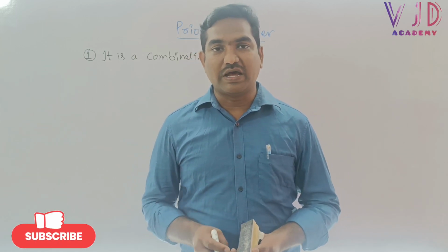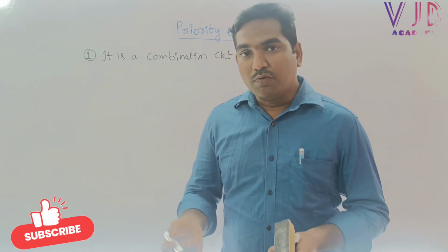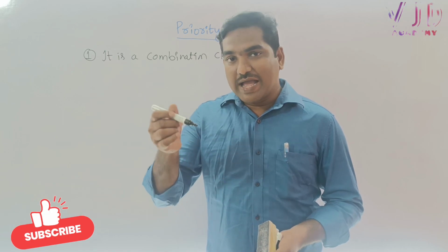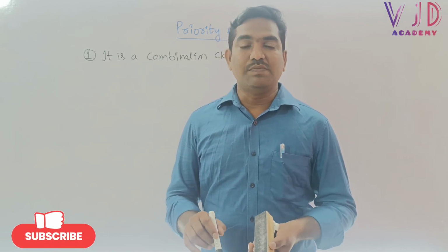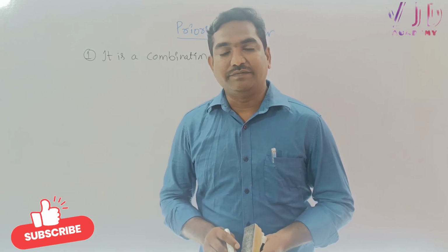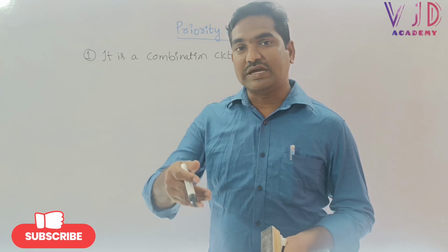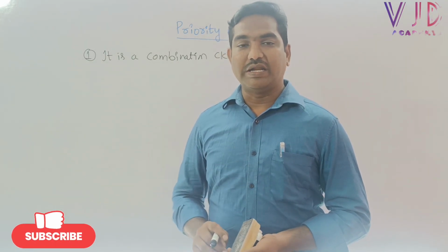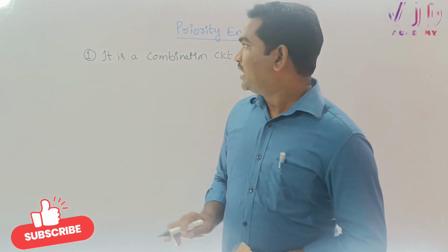What is the principle of this priority encoder? The topmost priority, the highest weightage input, will be considered first, and then this topmost prioritized bit, the highest weightage bit, will be converted into binary. How will this process happen? Let us try to understand.